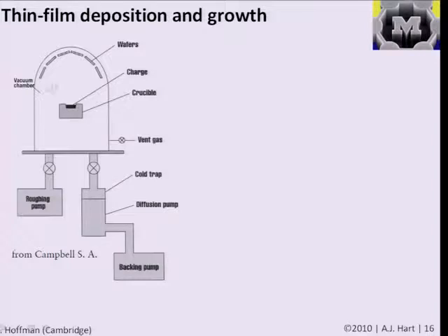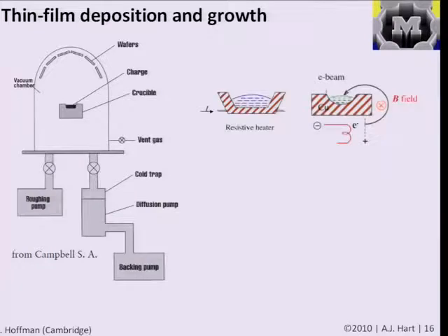So in another case, instead of having a cold surface on which you collected the nanoparticles that formed in the gas phase, you may, for example, have the same kind of crucible of material and have silicon wafers up on the top here and want to deposit the structures that you make onto flat substrates, and then you could grow them on those substrates and process them in different ways and shapes that we'll talk about later. And that precursor could be heated, for example, resistively. You could just have a hot wire and pass a current through that wire and melt the material like so, such that it evaporates above and then will condense on the cooler surfaces that are farther from this heated source.